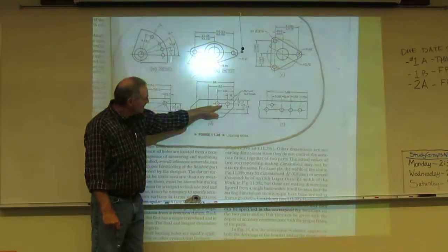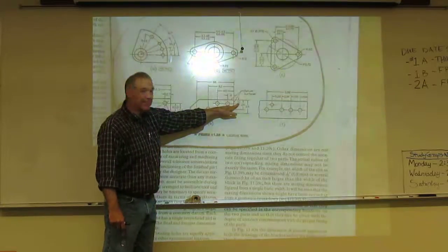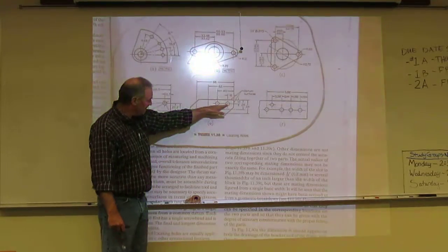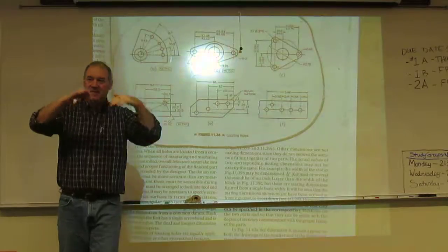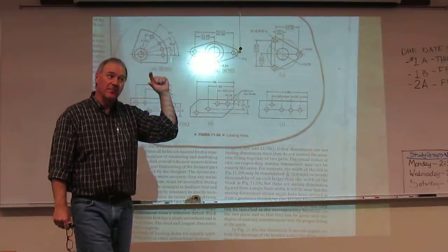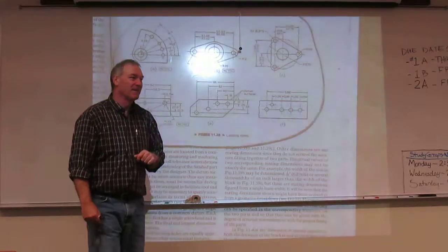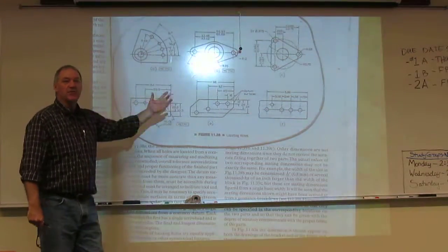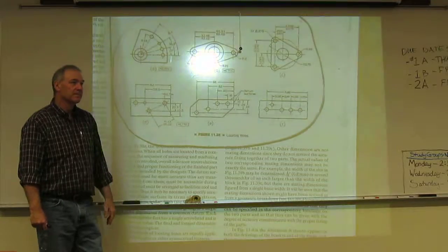Again, on this one, these 2 right here are located with that one. So take those center lines when they lay on the same axis and use them for multiple holes, because that means you only got to put one number for those. So in essence, we're cleaning the drawing up, right, using center lines.